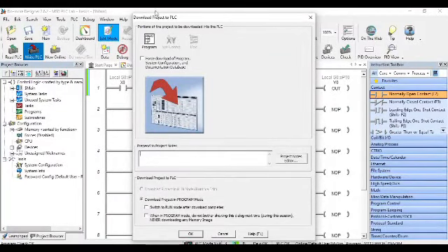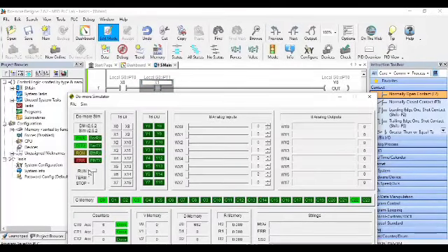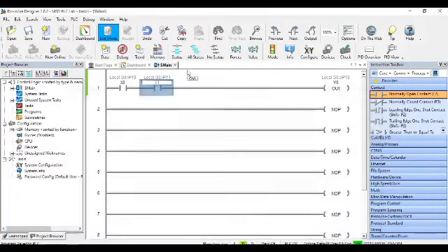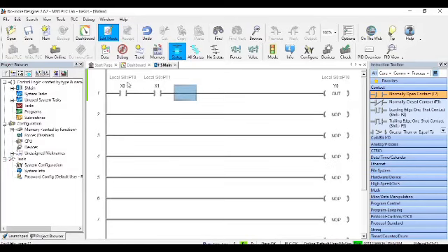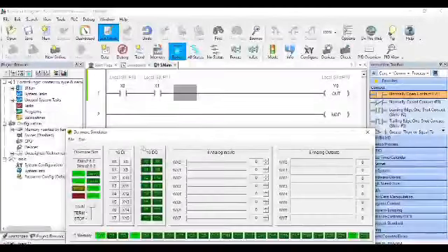and just a reminder that in PLC language, people usually say download to upload the code and upload to download. So it's the opposite. Download means that I'm uploading the code to my PLC. So I'll click OK. Everything is good. I'll run my PLC. I'll also run my status over here so that I can simulate this, and now you should see both at the same time.